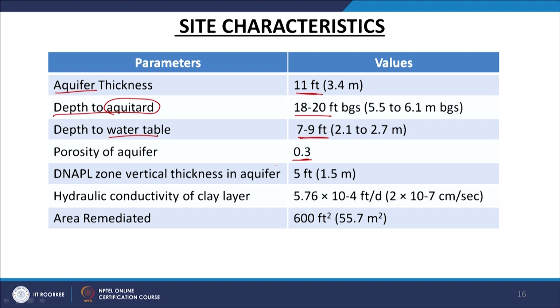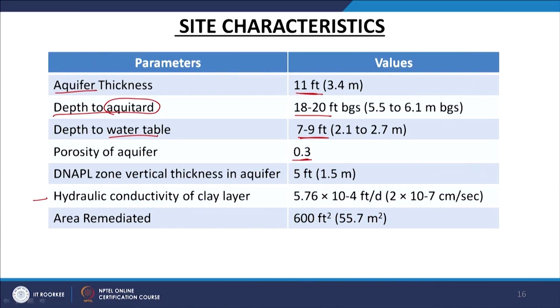And why is porosity a relevant or important aspect? Because obviously porosity and permeability, let us say, I guess, do we have that here, hydraulic conductivity, right. So, this I guess is a bit of an aspect. Again, we need the system to be relatively more porous, or have higher conductivity or hydraulic conductivity, so that it is easier to pump your surfactant through, right. So, that is something to keep in mind.